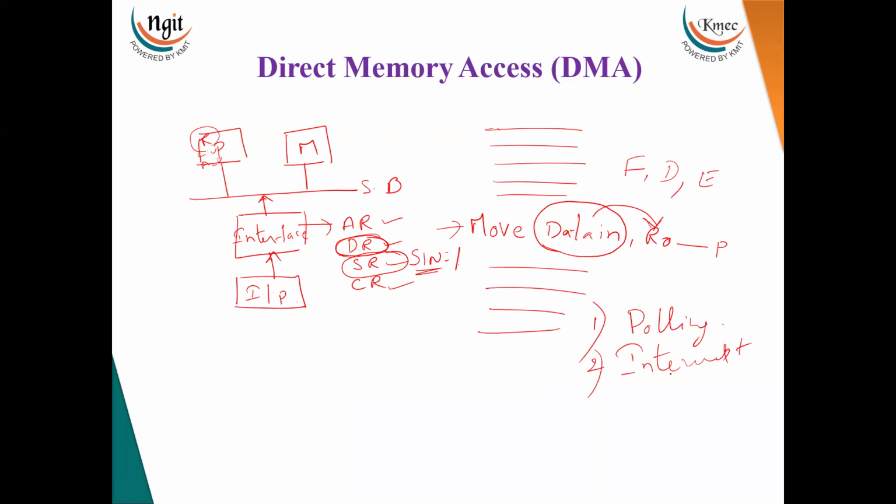In this also there is additional overhead, like storing and restoring the register contents onto the stack. Before executing the ISR, it stores the contents onto the stack, and after completing it, it restores them onto the registers. This is an extra overhead.